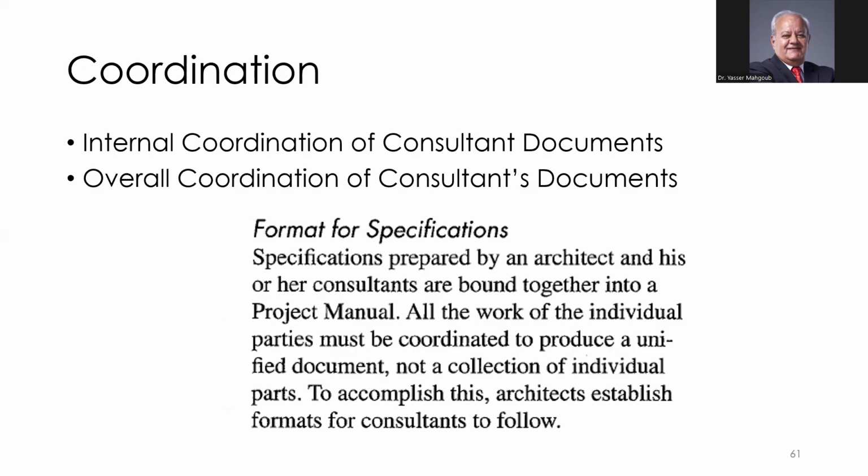Internal coordination of construction documents. Overall coordination of construction documents must be done in the office before they are issued to the contractor. The format for the specification for you and your subconsultants: the architect must make sure that all the formats are the same, all the drawing titles are the same, and they all correspond to each other. This is what we call the project manual.